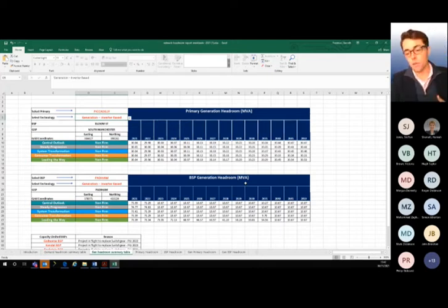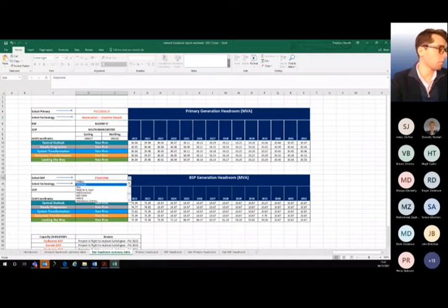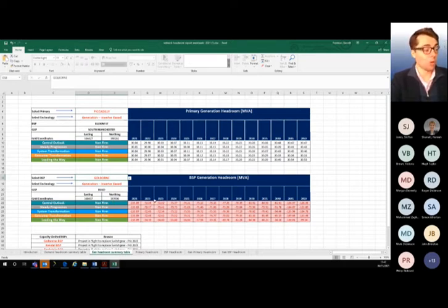With this Headroom report, we'll only put in things that are approved schemes that we're going to deliver. So if I was to look at Goulburn BSP, you can see that we're actually replacing the switchgear in 22, and you can see there's a marked change in Headroom. Unfortunately, it's still in the red, but that's just due to the amount of applications that are in that area. But you can pick different generation, and it'll give you an indication of what you can and can't connect.